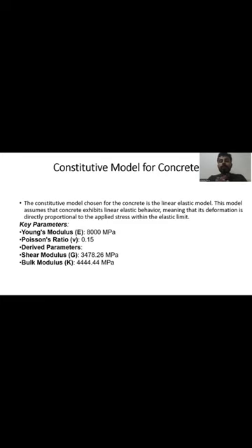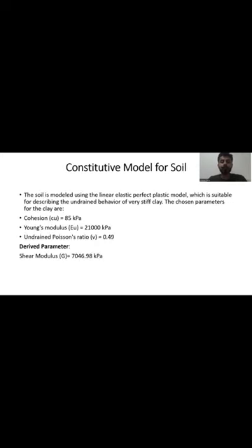The constitutive model chosen for the concrete is the linear elastic model. The model assumes that the concrete exhibits linear elastic behavior, meaning that its deformation is directly proportional to the applied stress within the elastic limits. With the help of the parameters which are being given, we calculated the shear modulus and the bulk modulus.